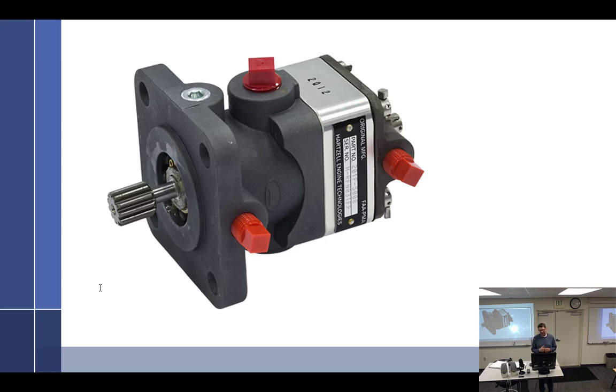Well, just looking at it, what would happen if I attach this to the engine and something happened to lock up the pump? It's a constant displacement pump, by the way, rotary vane. Shear shaft. That would stop the engine, wouldn't it? Something's got to break. Do you want it to break outside the engine or inside the engine? Outside. So the pump breaks right there. Shear shaft. That's why it's so thin right there. They wanted it to break right there.